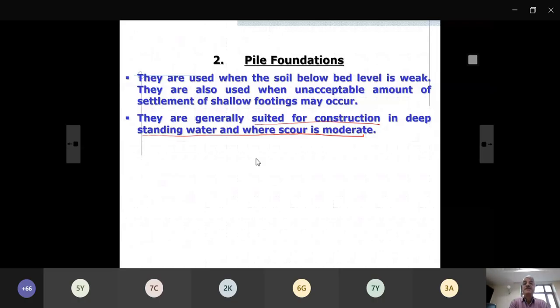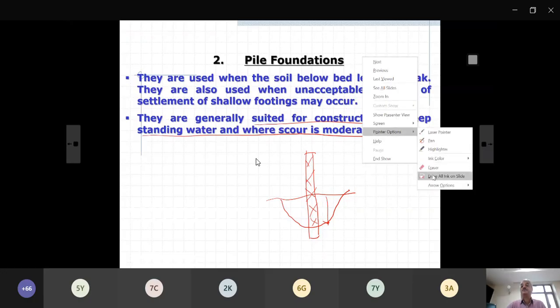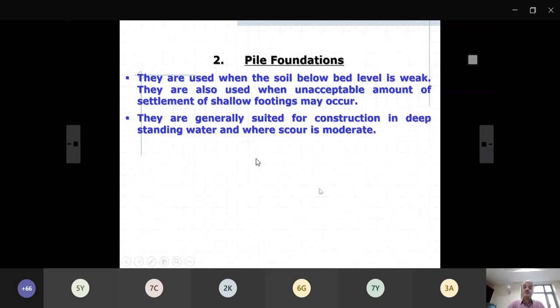If your scour depth, let us say you have designed a pile like this and this is your bed level. If your scour depth is very high, then in your design you will take this as freestanding pile. And if this height of pile becomes very long, very tall, your pile may become uneconomical. You may need very heavy pile. It may be costly also. Because it is a slender section, your L by H ratio sort of thing, that buckling comes into picture. Whereas most of the times you design your foundation for compression. Of course, you check for others, but compression is your main thing.